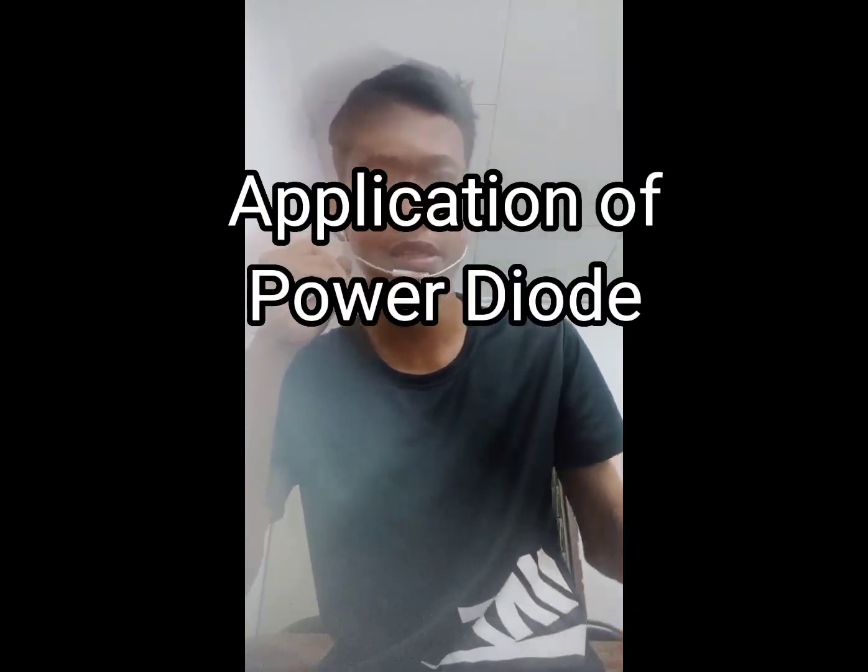Lastly, let me tell you about the application. The application of the power diodes includes uncontrolled power rectification. Second, it is used in applications like DC power supply for charging the battery, inverters, and AC rectifiers. These are used in snubber networks and freewheeling diodes due to their characteristics like high voltage and high current.